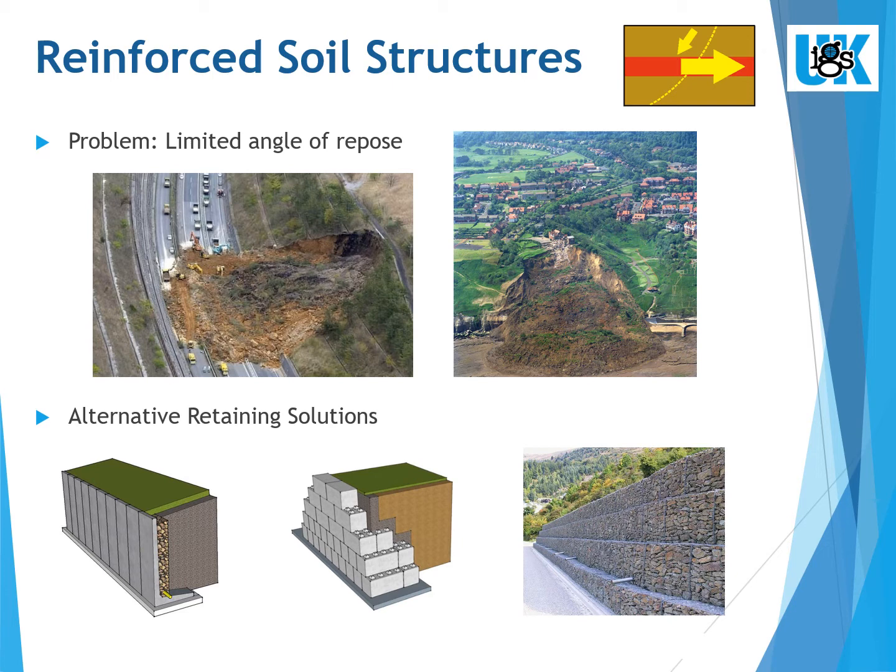The conventional solutions to steepen slopes or create vertical structures to change ground levels whilst minimizing land take would include reinforced concrete cantilevers, bored-piled or sheet-piled retaining walls, and mass retaining walls such as gabions, masonry, or crib structures. All of these structures are externally stabilized, with the structure working to restrain the soil pressure, and require an exponential increase in the stiffness or weight of material to resist the loading as the height of the structures increases.